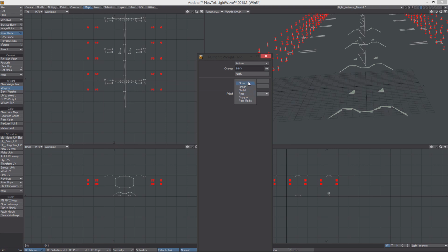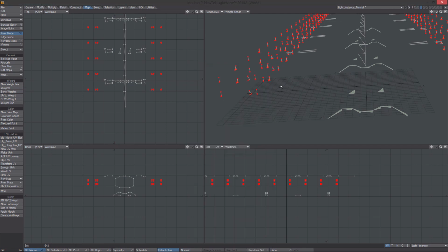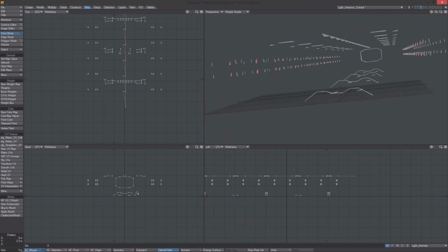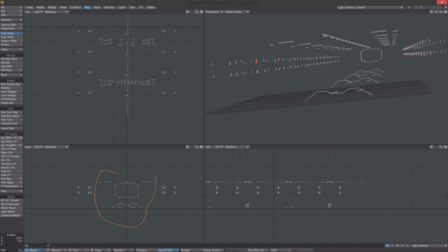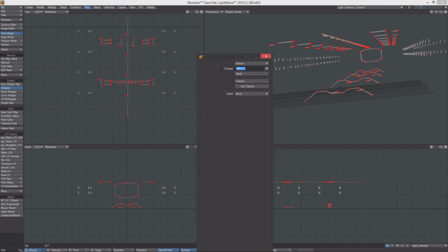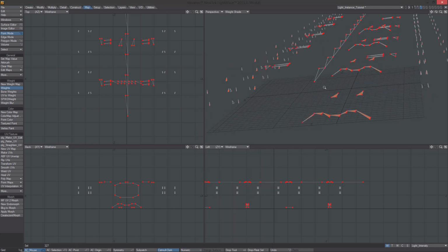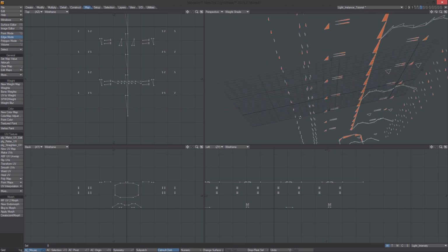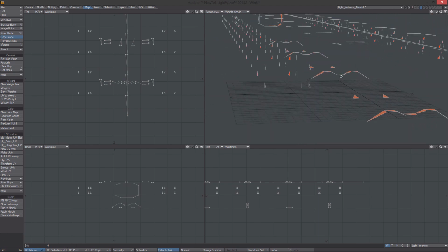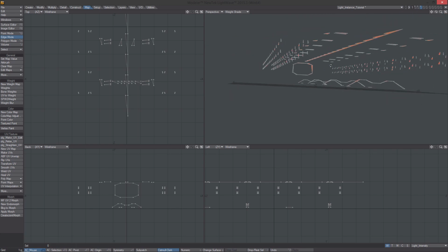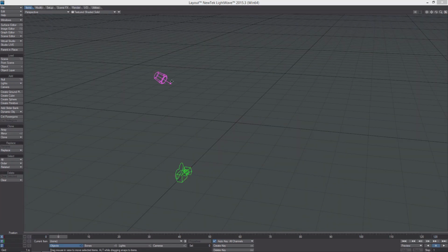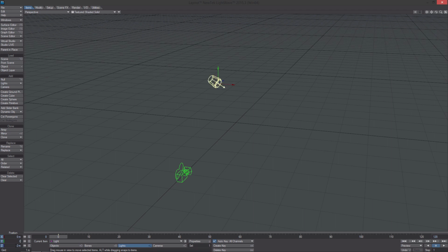So I'm just going to create them, outside lights. I'm going to put a weight of 100 on them. And then for the center lights, I'm just going to put a weight of 50. So now we can suck that value in when we instance our lights. We can use that value to control the light intensity, basically. So that's pretty much it. We have the weight map for the intensity and the color map for the color.